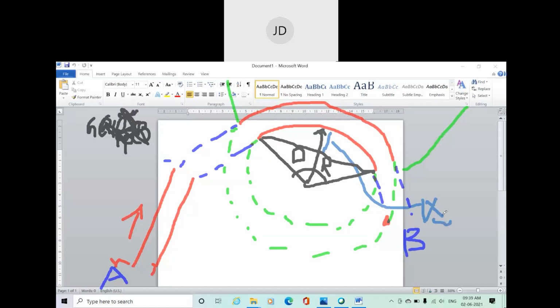It is called the versine, V-E-R-S-I-N-E. The length of the line joining the long chord to the peak of the curve is called the versine. So here we have radius, degree, and versine. All these things are there. One more thing you need to understand is that there is a standard value of radius. Do you know what is the radius for a straight line? Anyone?